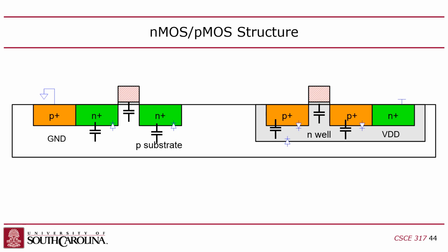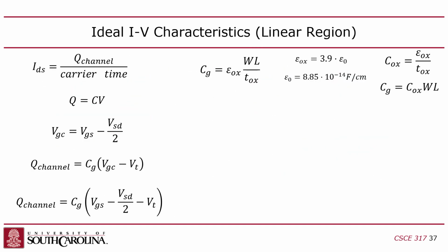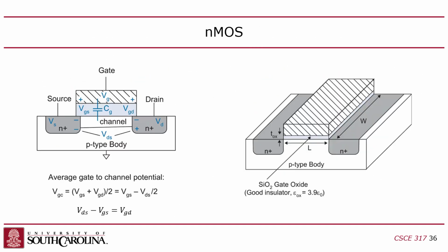And not only that, but the source and drain terminals, the source and drain diffusion areas, have to get wider. Their width is the same as the width of the channel, and it's impossible to tell that from that diagram. But if we look at the three-dimensional picture I've got, it's a little bit more obvious there. So if you look at the three-dimensional picture, you can see that the source and drain will also get bigger. Their width is the same as the gate width, right?